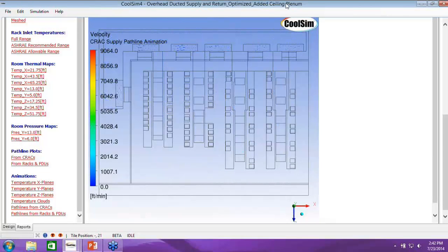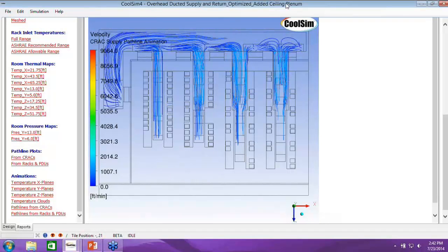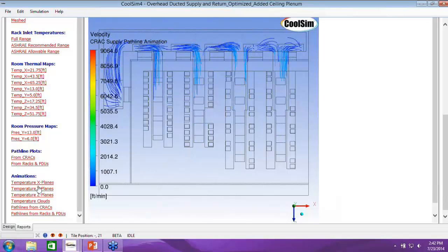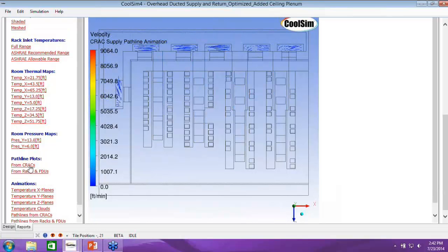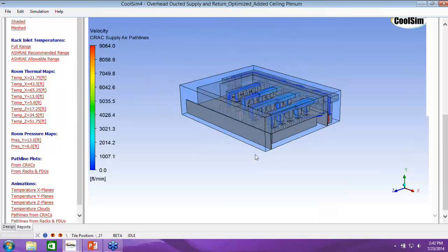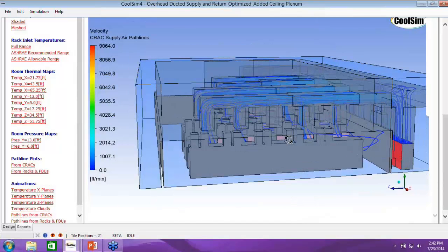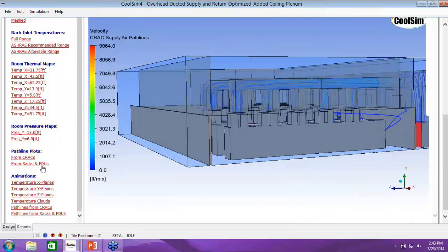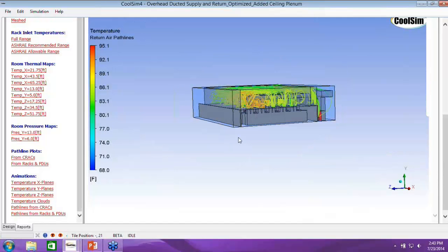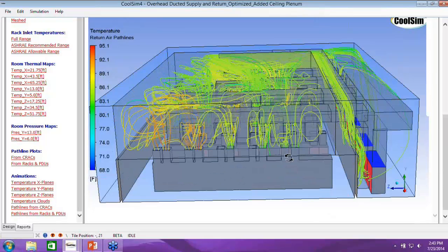Okay. So Paul, I'm going to put you on the spot here now. This methodology you have, that first you're fixing the airflow rate, and then you're looking at the RCI to crank up the supply temperature as much as possible. I would love to see that this process could be automated in one fashion or another. So you first put in the data you have now, and then the system steps through the same process as you do manually now, and it stops when all the metrics are close to 100%. Yes, you're absolutely right, Magnus, and I agree with you.